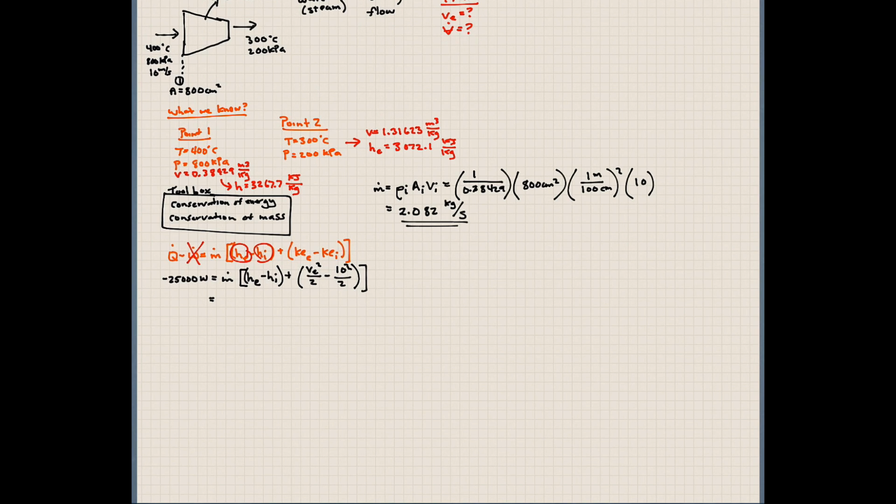And remember, this is a steady operating system, and there's no other inputs in our nozzle, so we don't have anything else coming in. So our mass flow rate is constant, or it's conserved. So what's coming in is coming out. That'd be the same value at the exit. So regardless of where we take this mass flow rate, it is the same at the inlet or exit.